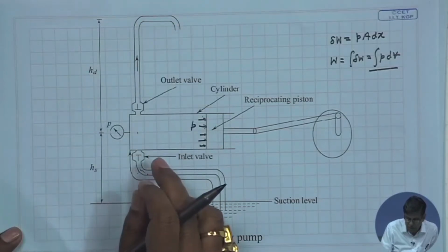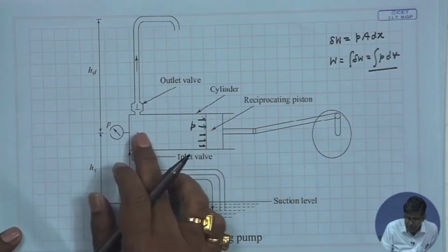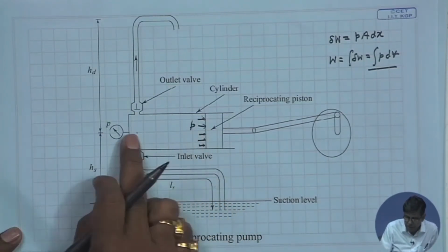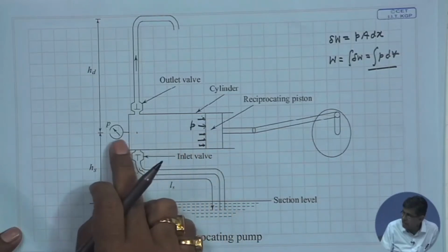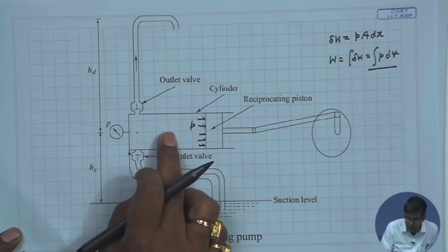So, therefore, during the suction stroke there is zero delivery rate, and during the delivery stroke there is a delivery rate, but the piston executes a simple harmonic motion. Initially there is acceleration and then deceleration, resulting in a maximum velocity at the middle of the stroke.